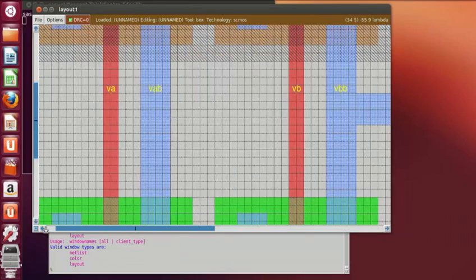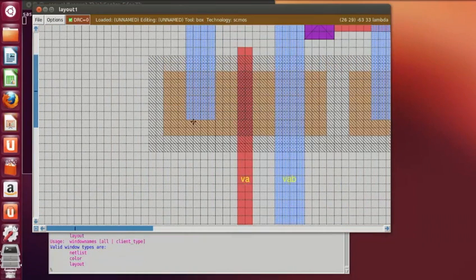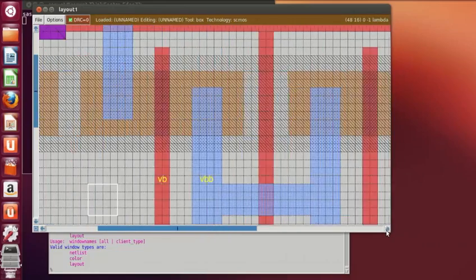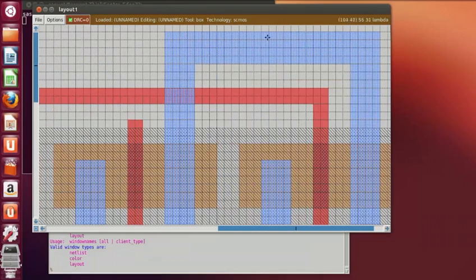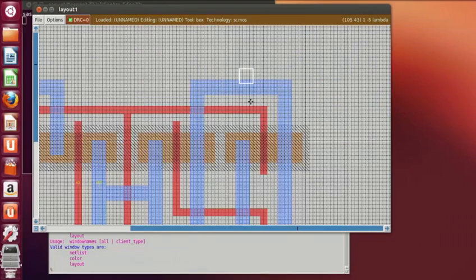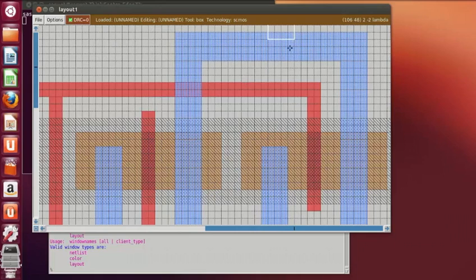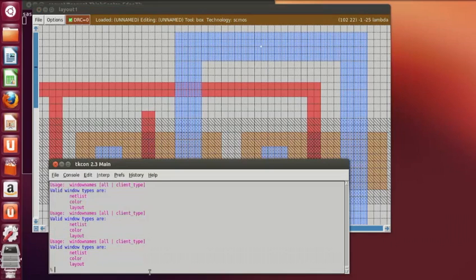Once you've understood the schematic, then the twisted schematic, then it's very easy for you to draw the layout. Okay, before going to contacts, we can label the other terminals left. The other left is only the output. So this is the output. So select, right click, and then label V out.